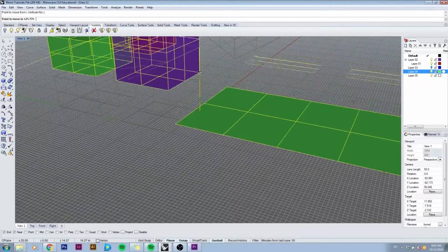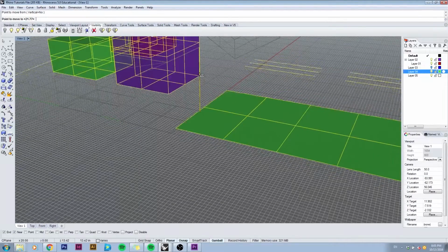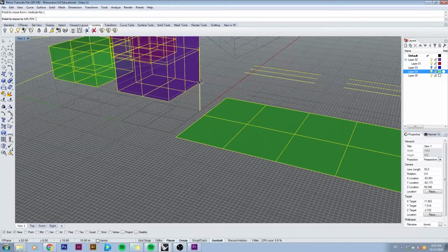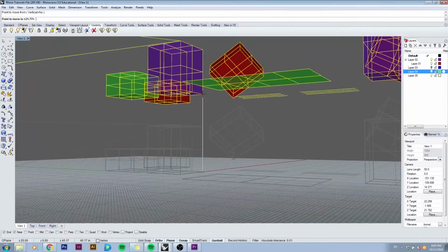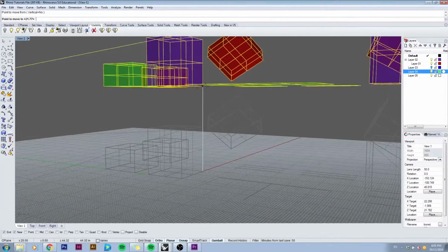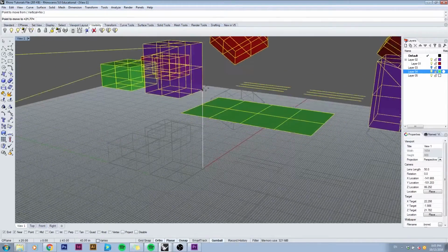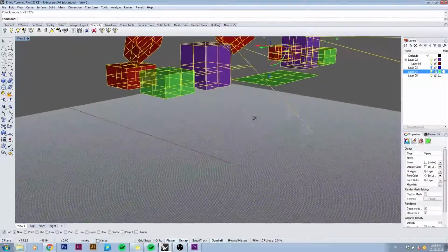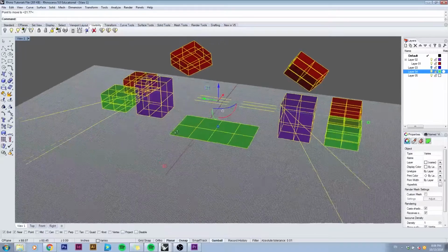If I want to go past this edge even higher, I can actually lock my movement only on this edge by hitting Tab while near is active. This will create a white line that will limit my movement of my model only within this edge. And now I'll click to drop the model in this place. So now my model is moved.